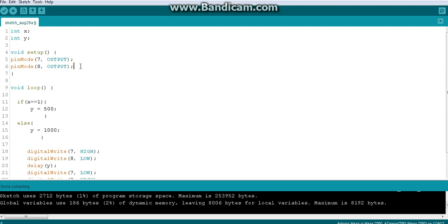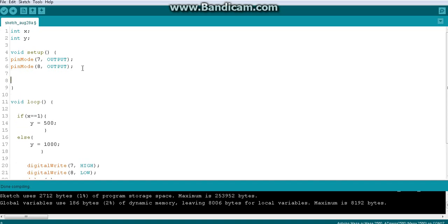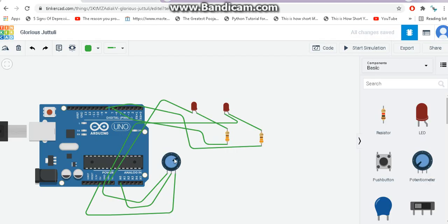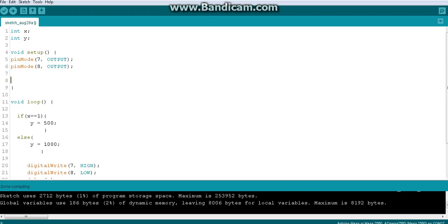Since I am going to connect that variable resistor, that means this one, okay guys, you have seen this, right? We have studied about this already, right? Since I am going to connect this to A0 as usual, I am going to add that code here as pinMode A0 is input. I am just trying to add that analog input code inside here just to make our scenario happen.